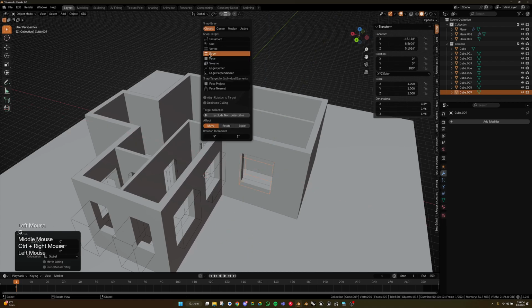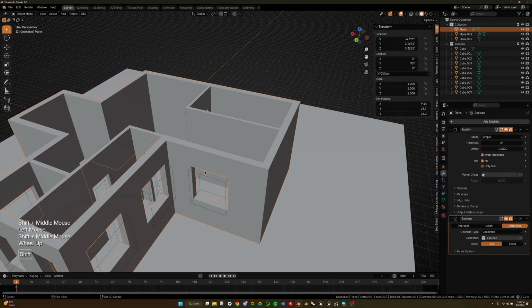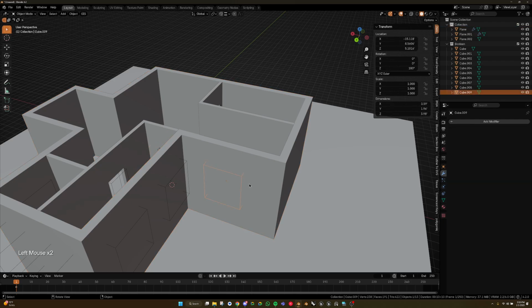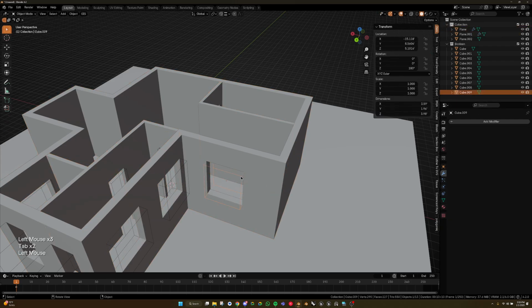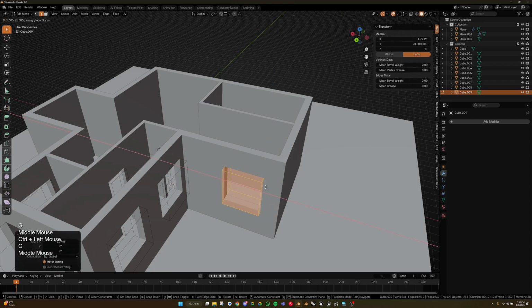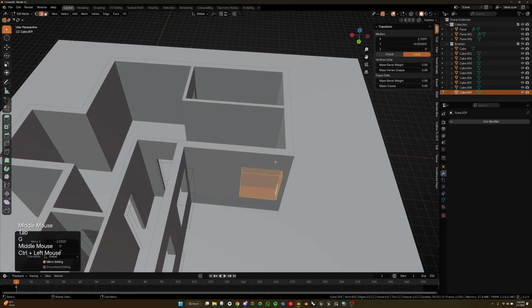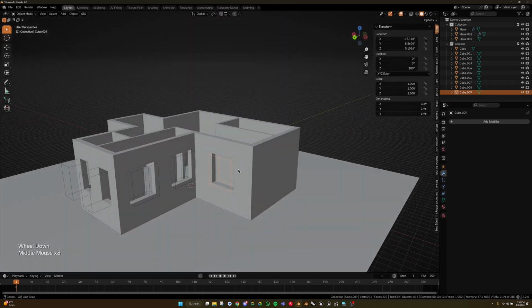And let me see something. If you want to move this a certain distance from the wall, you can turn it off. I think actually you have to be in edit mode for this. Go to edit mode, move it to the edge, and then move it over, and then you can specify your distance, like 3 feet from the wall or whatever. And you could also do it from the interior wall too. Move it over 2 feet from the interior side of the wall. And then there you go.